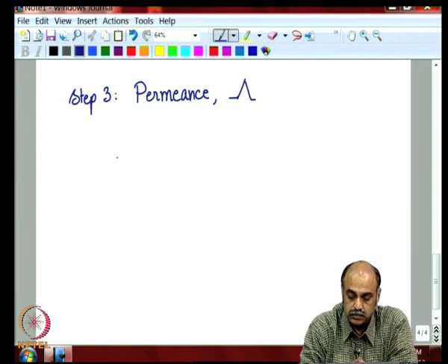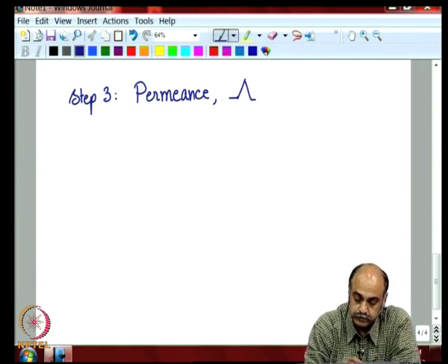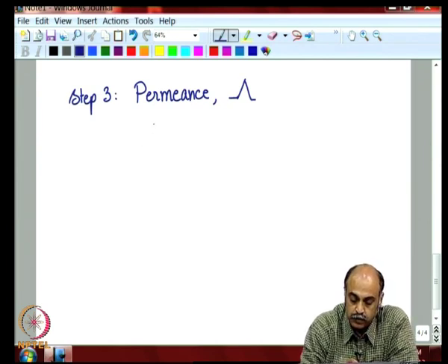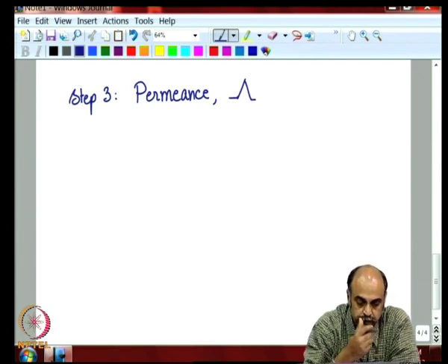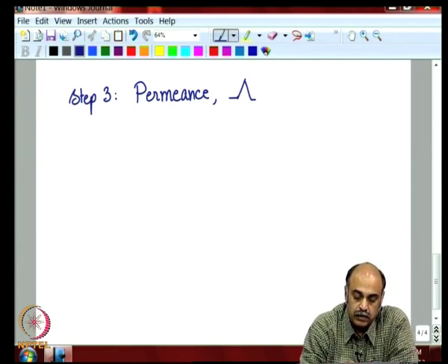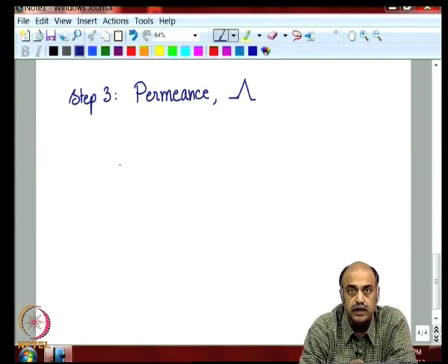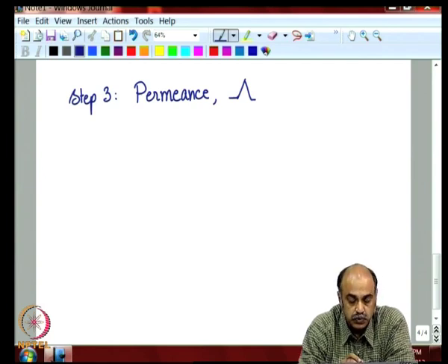Now, the permeance. Sometimes inductors are manufactured with the air gaps distributed throughout the core uniformly, and these have much lower relative permeability than the transformer cores, which have very high permeability and permeance, and there is no need for energy storage.